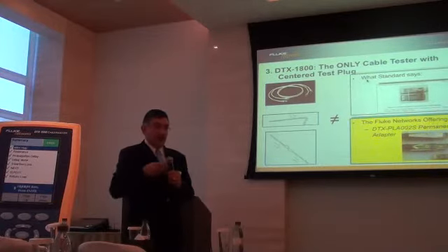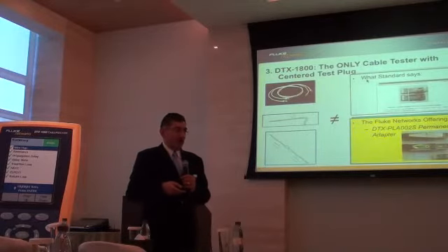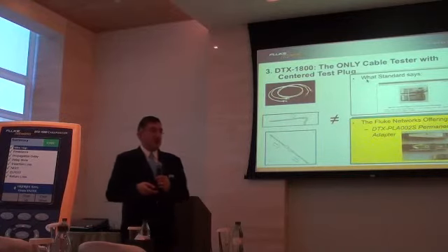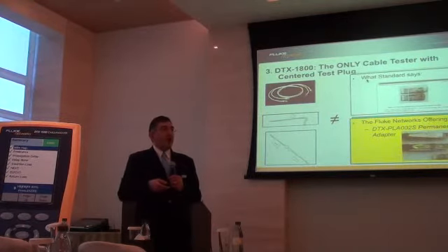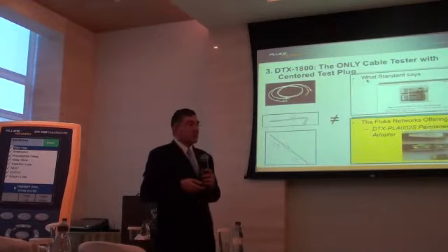You can say I can test based on channel 11801 or 11801. You can say I can check for Cat6 or Cat6a on TIA 568. It's totally different than application. They don't compare. I can easily pass application standards with even a copper... I think I was not able to make myself quite clear.